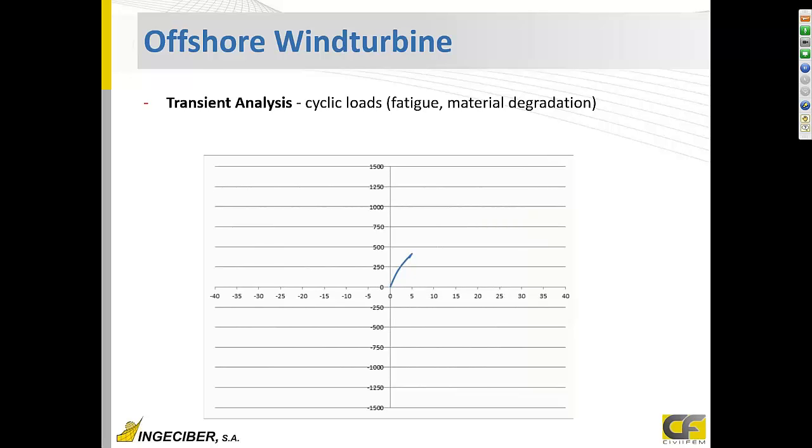With this sort of analysis, these cyclic loads, we can analyze fatigue. In this case, CivilFEM does not check for fatigue at the moment, but you can get the maximum and minimum stresses in some of these cycles and validate the fatigue of the model separately.